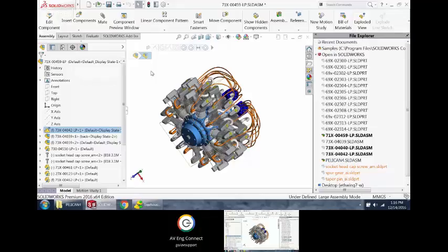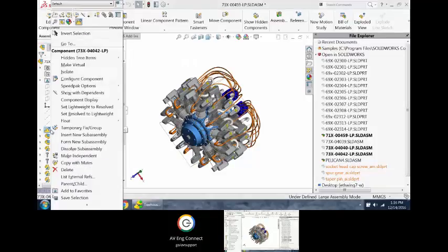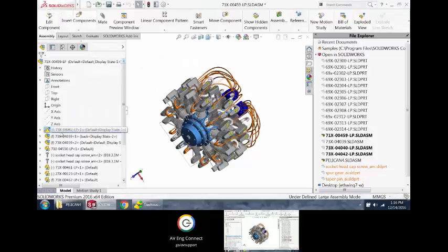When we're talking about performance at assembly level, there's the hierarchy, how many parts you have in, what type of information you're bringing in. And there's also the mate information coming through there. So the stuff that needs to load, if I turn off this flexibility, it doesn't have to load all of those mates down at the subassembly level.